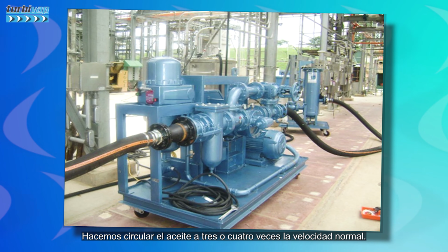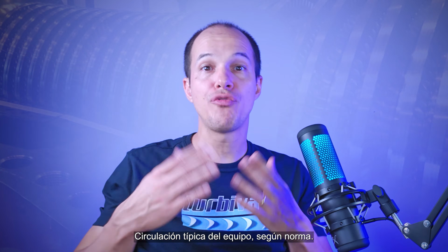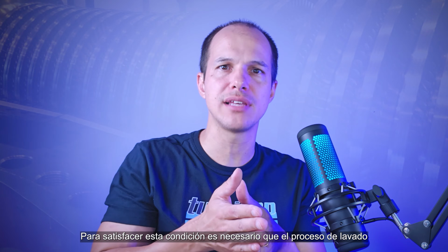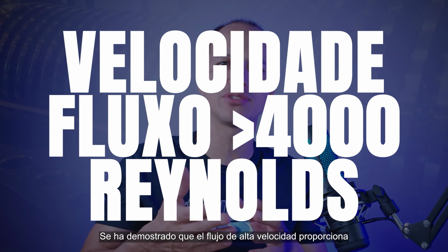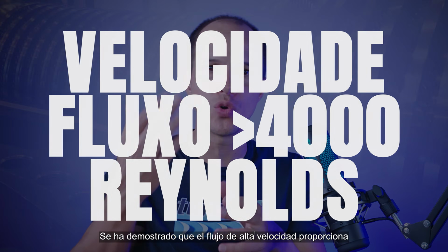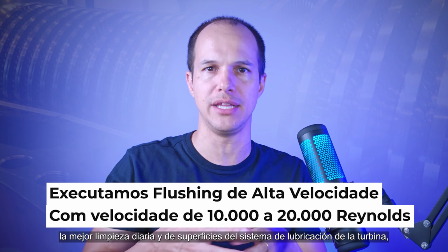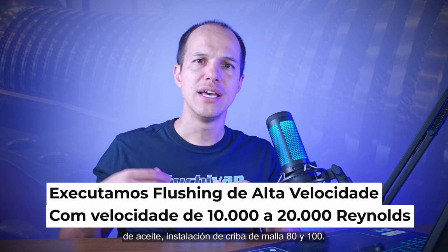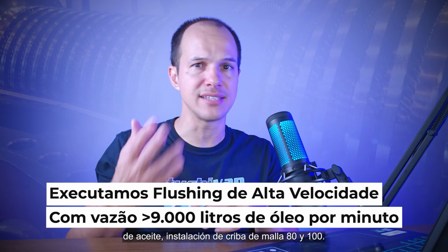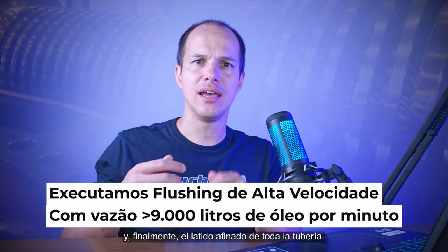To begin with, let's understand the term high-speed. This concept of high-speed oil circulation during flushing is the main difference of this flushing. In this case, generally with the use of external pumps, we circulate the oil at 3 to 4 times the normal speed of typical circulation of the equipment, according to the standard. To satisfy this condition, it is necessary that the flushing process reach a flow velocity above 4,000 Reynolds. High velocity flow is proven to provide the best cleaning of the surfaces of the turbine lubrication system.